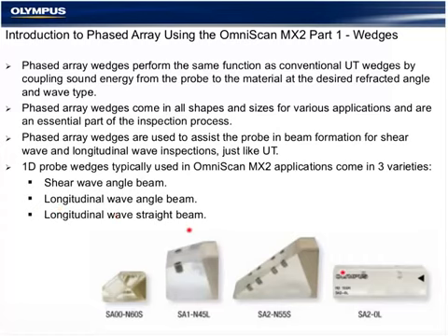This probe is designed mostly for coverage of what would normally be done with a 0 degree inspection. But we can also generate longitudinal angles and traditional sector scans from this wedge. Most everything we do that's not customized would fall into one of these three categories.